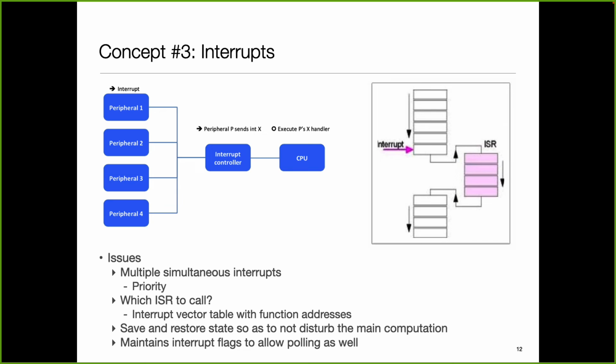Just one thing to keep in mind about interrupts. An interrupt handler at some level looks like a function, but it has some key differences. Usually when you get into an interrupt handler and you are writing the code, there are a lot of things you could do in the regular code that you can't do in the interrupt handler. In particular, you can't do anything which will cause the processor to wait, because then the whole thing will hang.